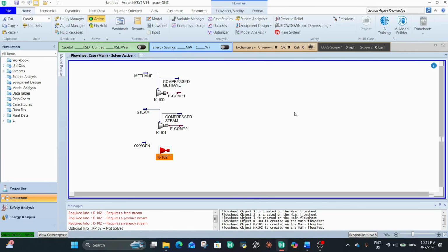The reason it's called partial oxidation is because you use oxygen to do that. In an event where you use air, remember that air is predominantly made up of nitrogen, and nitrogen is an inert gas. It doesn't partake in a reaction, but by all means, it will dilute your syngas, and you will have to separate the nitrogen in the long run.